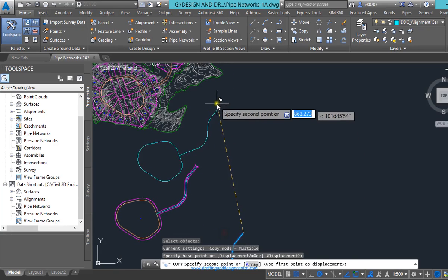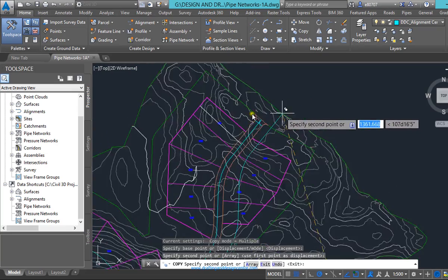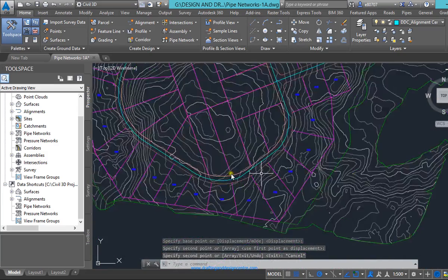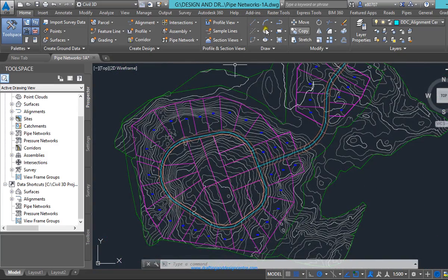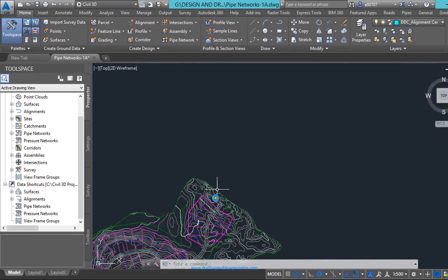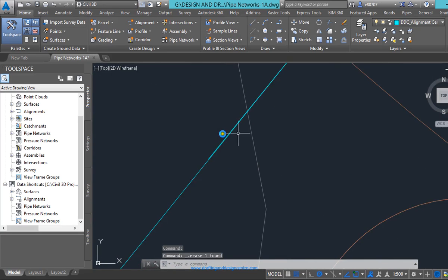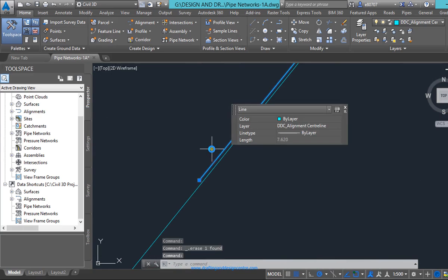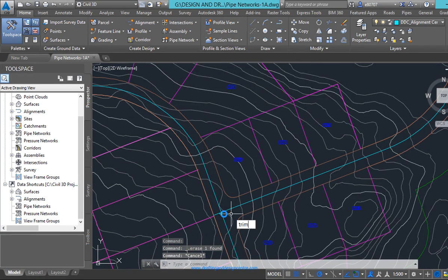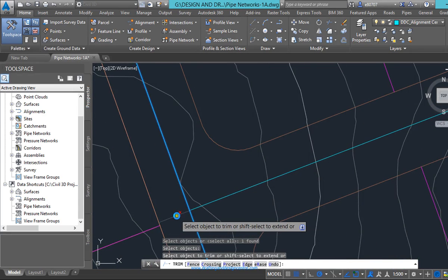On this end, I can put that back to here. And as you can see, my nice tidy centerline alignment is there. You can check it out. You can check the curve after creating the alignment, which I'm going to do shortly. You may need extra precision, which I haven't followed. The objective is just trying to show you how we can start up a subdivision project.